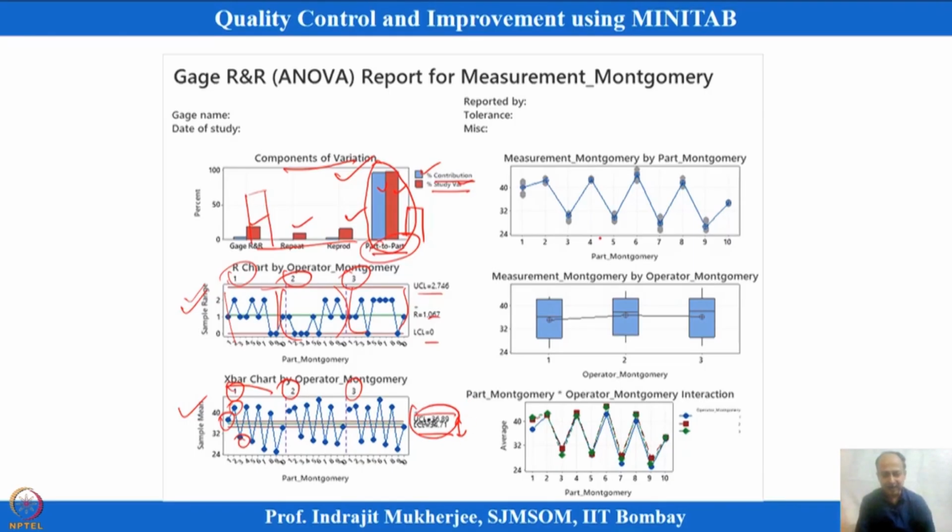So, this is expected. Whenever you are measuring the parts, you have calculated the control limit lines using this R bar information over here and used the control chart. So, part to part variation will be there over here. So, with 10 parts, most of the time we will find points outside the control limits. This is not unnatural in the case of measurement system analysis, it is expected. If it is not, then there is a problem.